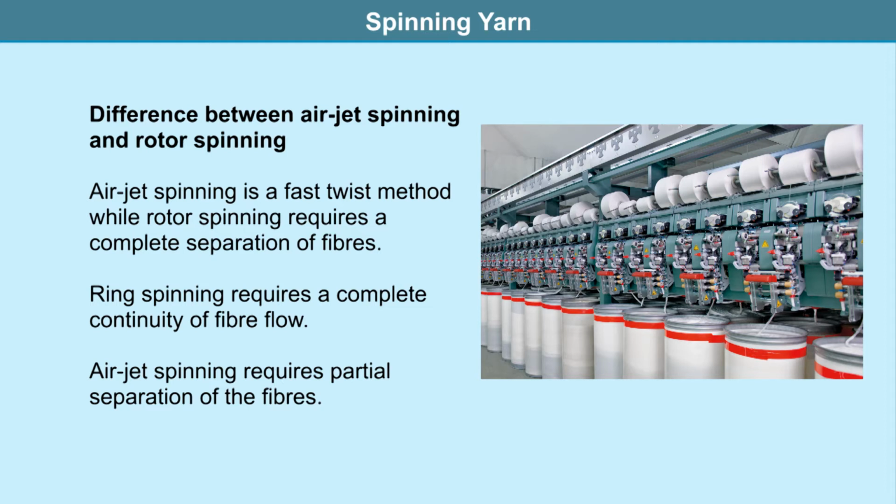Very fine yarns cannot be run on this spinning system because the strength imparted to the yarn is not enough to withstand the rigors of further processing. Some of these machines use a two sliver input. The slivers are drafted through the equipment to a dual head spinning nozzle which spins the yarn in opposite directions. The two yarns are then brought together and create a 2-for-1 twisted yarn. The yarn passes through a yarn cleaner and a waxing device before it is packaged. The process produces a relaxed yarn with about the same tensile strength as ring spun yarn.